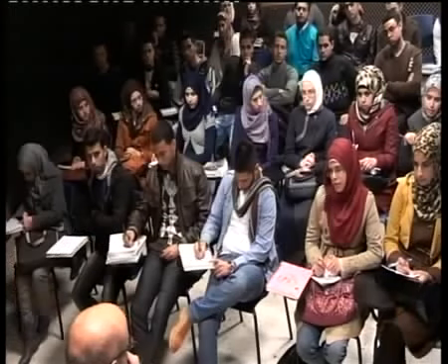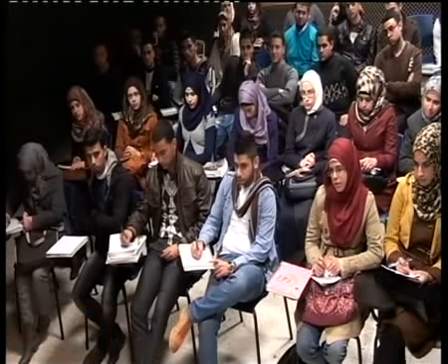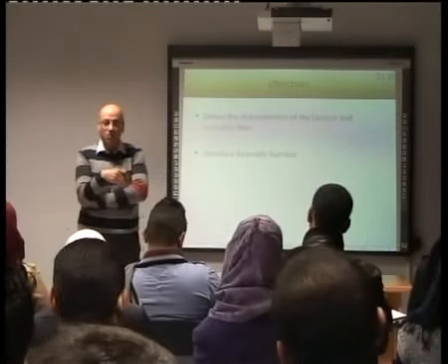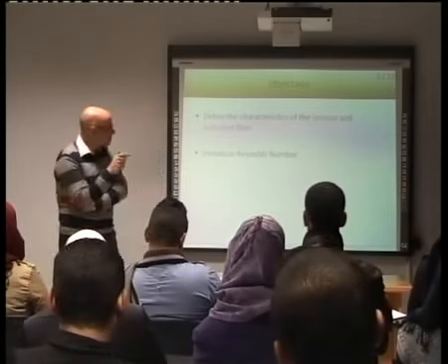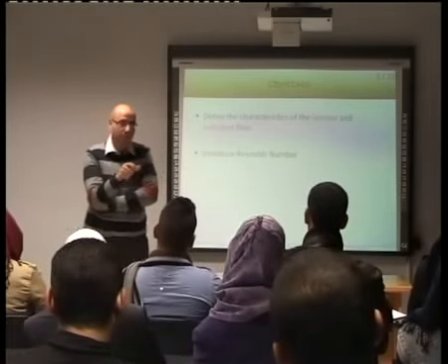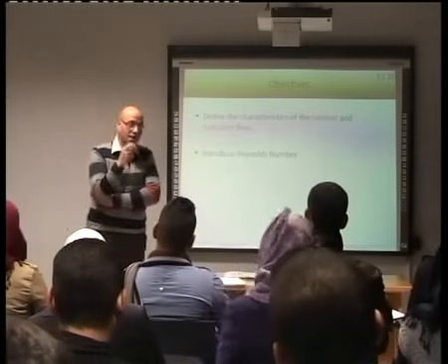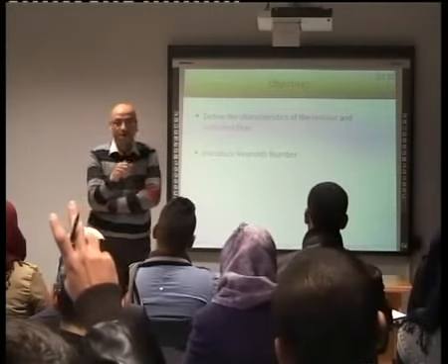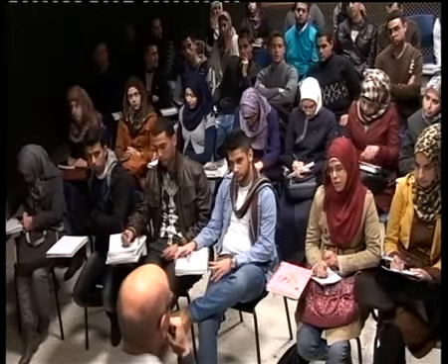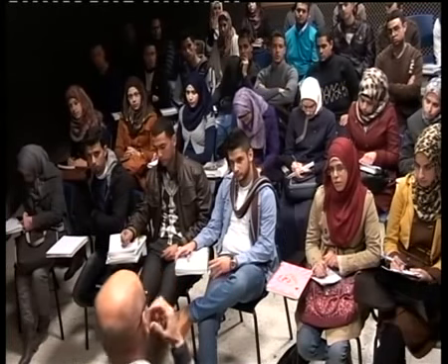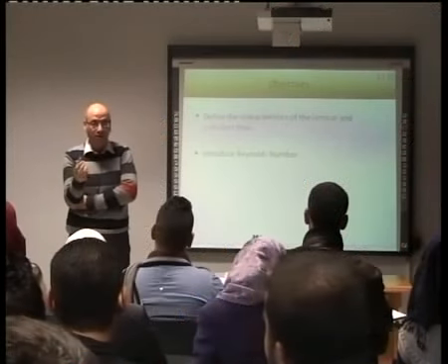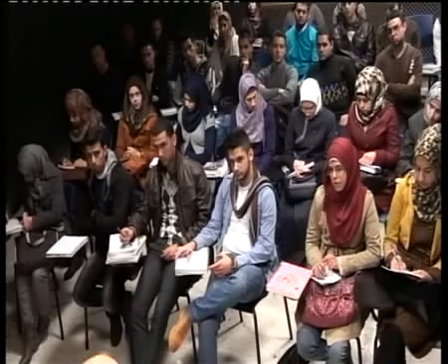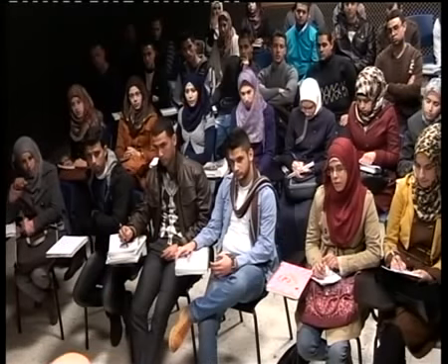Reynolds number less than 2100. Yeah, 2100, or you can find sometimes 2000, sometimes 2300, something in that region. If the Reynolds number is less than that number, then it is laminar. But I'm not talking from a quantitative point of view. I'm talking from a descriptive point of view. Mainly, the flow is mainly affected by viscosity. Yes. So the impact of viscosity on the flow is major. And it exceeds the impact of what? Of friction. No, it's friction. Viscosity is friction.